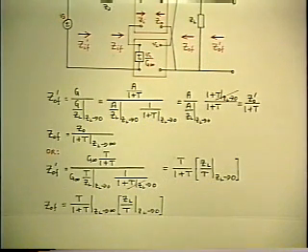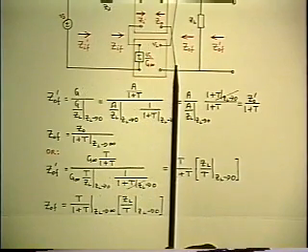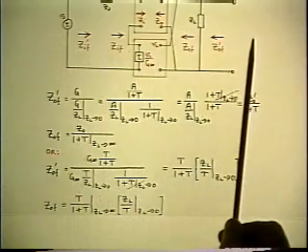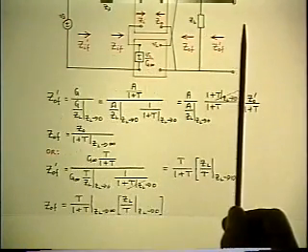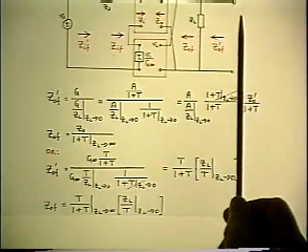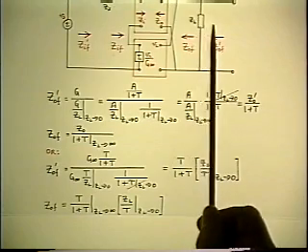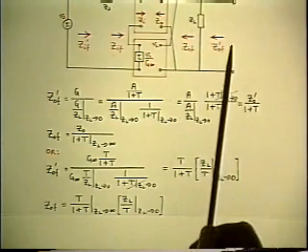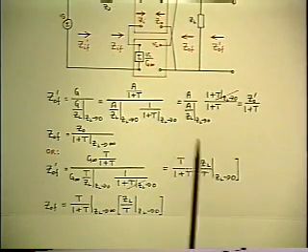And it's not surprising, of course, because this connection of feedback is making the overall amplifier act more like an ideal voltage-to-voltage amplifier, which means its gain becomes insensitive to the load impedance, and the only way that can happen is for its effective output impedance to be much less than the load impedance. So everything fits together.